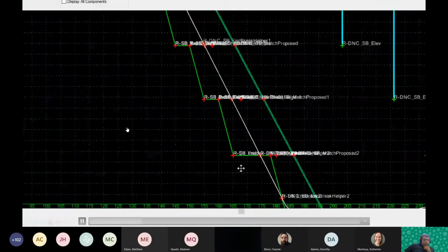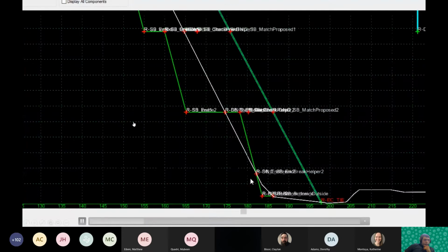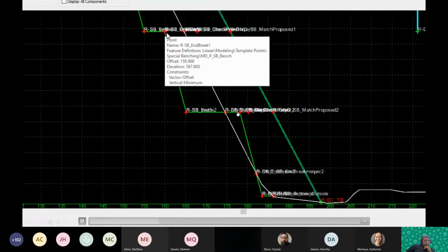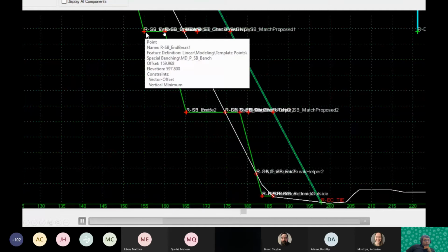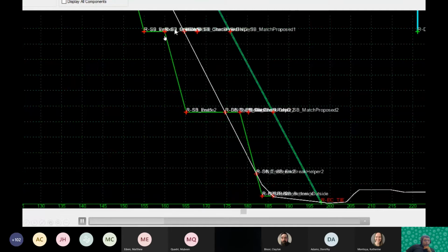So right there, I did edit station. And when I do edit station, I'll go over this a little more, but what I wanted to show is that when I edit station, you can see those points are showing up right where the existing ground is coming through. Okay, and so I'm going to show how I've set this up. It does this kind of automatically, but it only does it when you actually come to the other side of your ground. Like up here, where I'm still on the left side, the cut side, it didn't do that because it didn't need to, right? But over here it did.